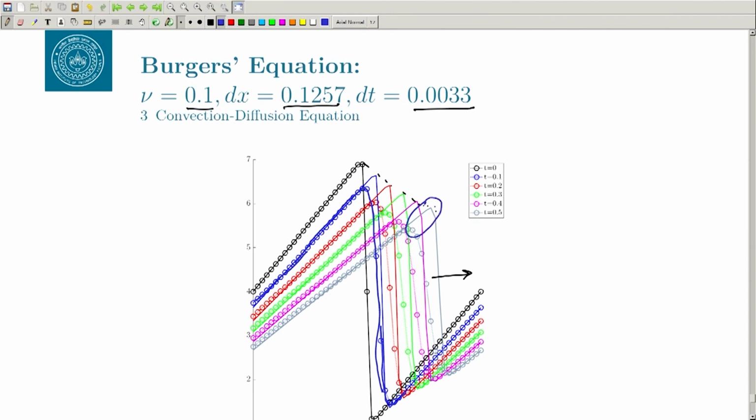Here you can see this is the peak in the analytical solution, and this is the peak that you are getting in the numerical solution, and similar behavior you would see downstream also. If you improve the grid size and make it finer, it will become better, but regardless of that you will have certain numerical diffusion that you cannot avoid.